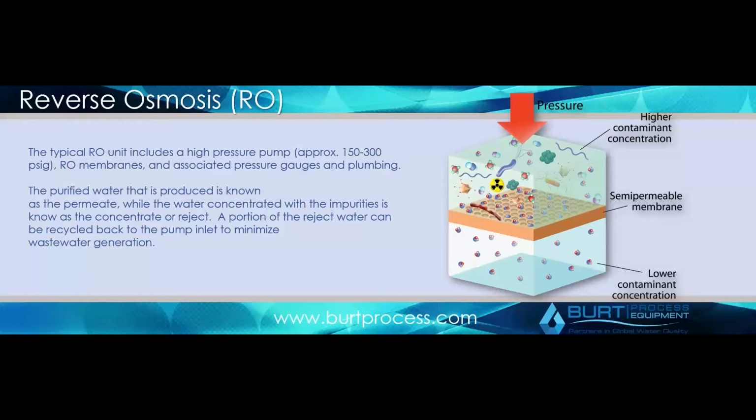Optimizing the permeate out, as well as the water quality that you get out of it, is typically done with what's called an RO projection. And I'm going to go through one here in a couple of minutes that shows how you can go into the design of an RO system to optimize the water quality as well as the water pressure and constituents that you're trying to remove from your system.